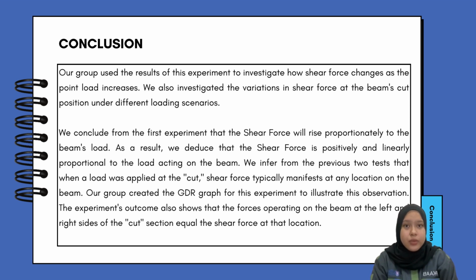We infer from the previous two tests that when a load was applied at the cut, shear force typically manifests at any location of the beam. Our group created the graph for this experiment to illustrate this observation. The experiment's outcome also shows that the force operating on the beam at the left and the right side of the cut section equals the shear force at the location.